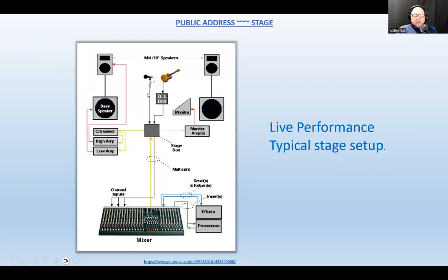So you bring the signal from the instruments, microphones, whatever is on the stage, and that is delivered into the mixing board. If it is an analog setup, you are going to have something called a snake. A snake is a multi-pair cable, quite thick actually, and they come in 50-foot lengths, 100-foot lengths, and so on, in order to deliver the signal to the mixing board.